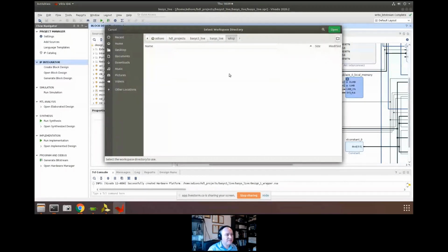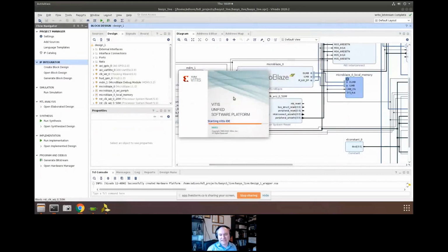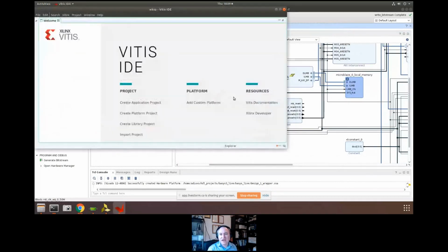I'm going to click on Create, and I'm going to click on Open, and it's there that Vitis is going to put all my files. So in a minute, when I import the XSA, it's going to be there where everything gets pulled through and gets started working from.